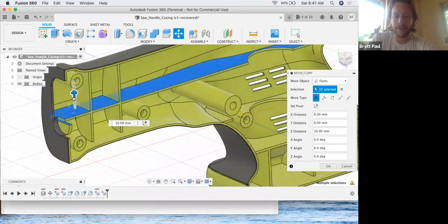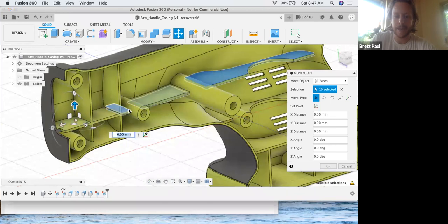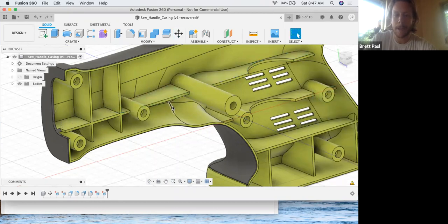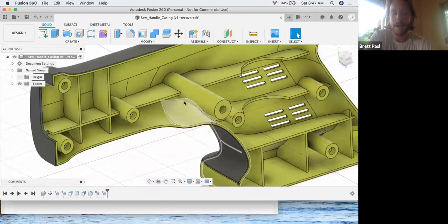And if we move it back down, you see now that it successfully updates so that our rib doesn't go through the boss, it just goes up to it. But again, let's click cancel like they've asked so that it goes back to its original place. And that's that. So super quick, super effective. Definitely the right solution. Direct modeling is the right solution in certain instances. I still think parametrics is a better approach as long as it's efficient and it makes sense. I would say I default to parametric modeling and then might use direct modeling when it's absolutely necessary.